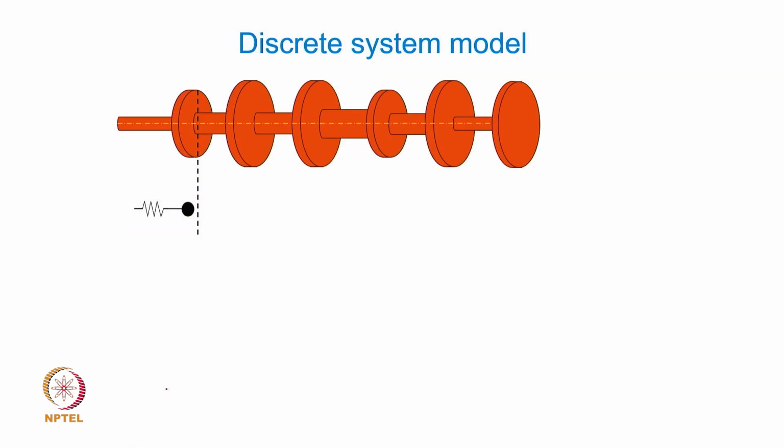Anyway, this is the basic process that we follow: we discretize this entire continuum into small segments, and each segment has a lumped mass element and the remaining part is the stiffness element. Now, if this is to be treated like a torsional vibratory system, the gearbox which we saw, the more dominant vibration is going to be torsional vibration, going by the torque transmission that happens in it.